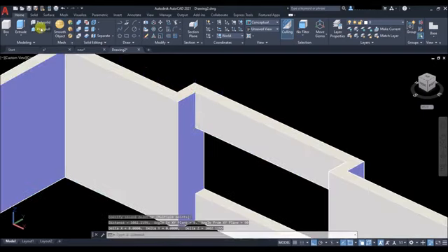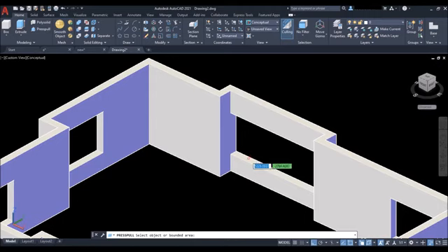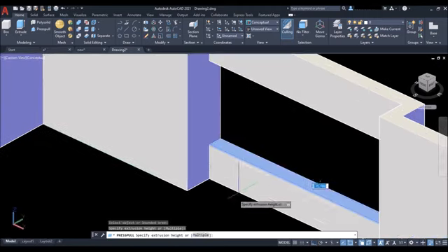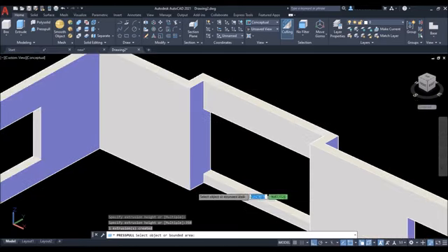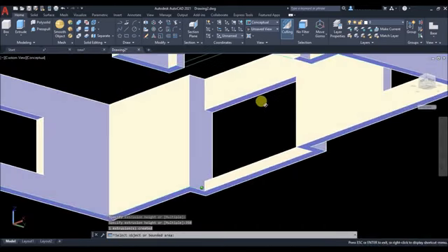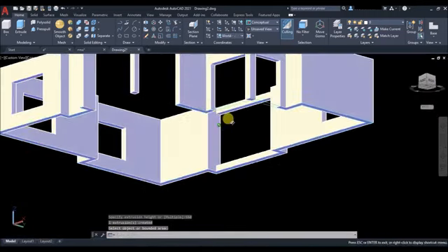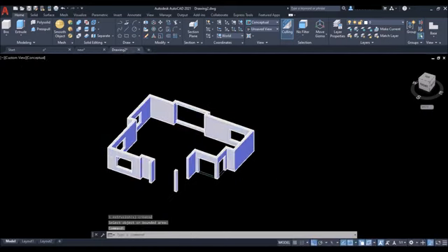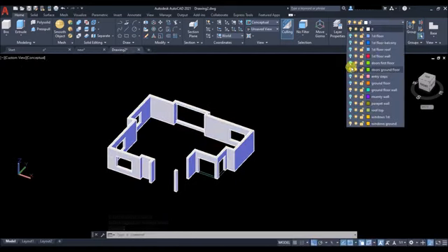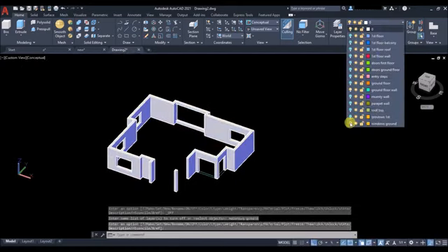Okay. Click on press pull tool again. Select this face and press pull cut it downwards by 350 units. This face upwards by 550 units. Always right click to exit from any command. Now turn all the layers off again except the zero layer.